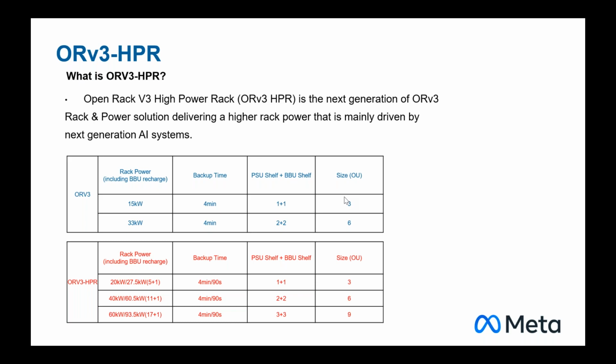Okay, yeah, we've got customers still at 208. The 230, 240 is really what NVIDIA pushes people towards. And in addition to what David Sun is asking, I'm looking at the input connector to the power shelf, from Positronic, Amphenol and others, and trying to get that one pushed up in current as well. Yep, makes sense.